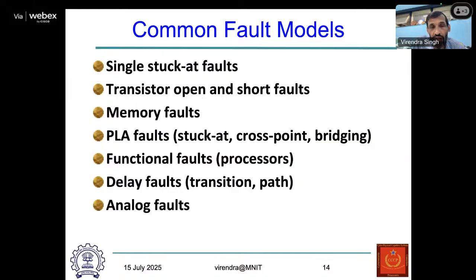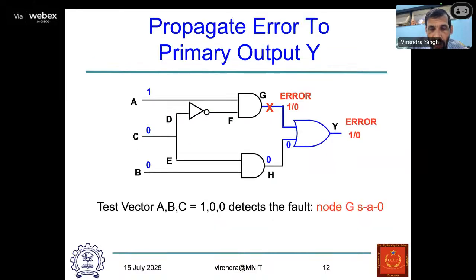So that means they don't have a logical defect or logical fault, because if I provide enough time, that particular net, for example here if I say z, can change from 0 to 1 or 1 to 0.